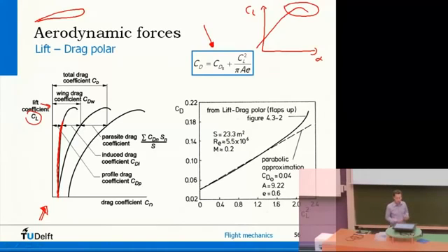But of course, I've just discussed that there's also a three-dimensional factor, that as soon as we start creating lift, we start losing energy in the atmosphere, and therefore aerodynamic drag increases. So if you just look purely at the wing, if you don't create lift, so if we're on the x-axis here, then the drag would be the same as the two-dimensional case.